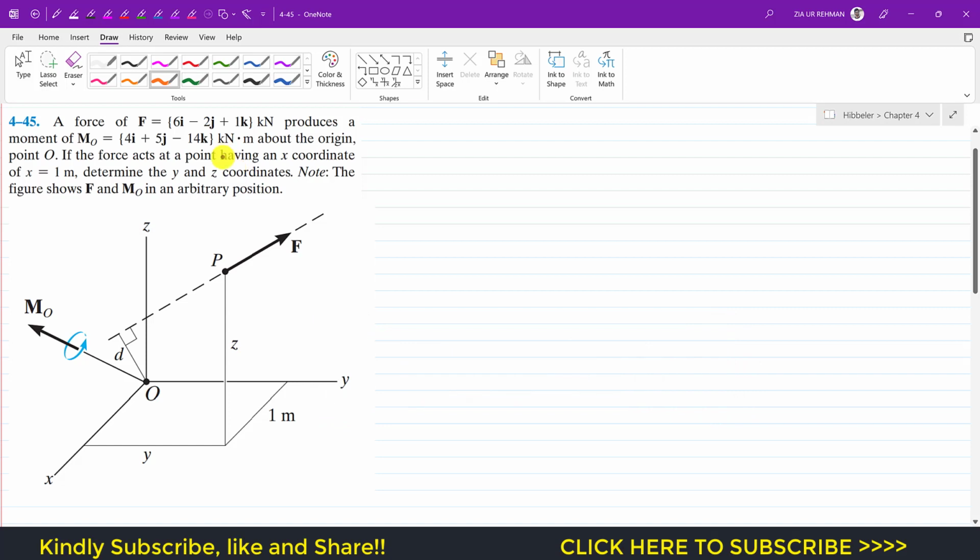Now we are going to solve this problem which says that a force F, given in Cartesian vector representation as 6i minus 2j plus 1k kilonewton, produces a moment of this much kilonewton meter about the origin point O. If the force acts at a point having an x coordinate of 1 meter, determine the y and z coordinates. Note that the figure shows F and MO in an arbitrary position.